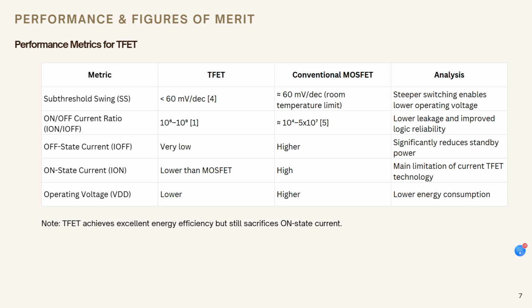Looking specifically at the off-state current, TFET has a significant advantage. Since current only flows when band-to-band tunneling occurs, the leakage current in the off-state is extremely low. As a result, standby power consumption is greatly reduced, making TFET particularly attractive for low-power and always-on electronic systems.